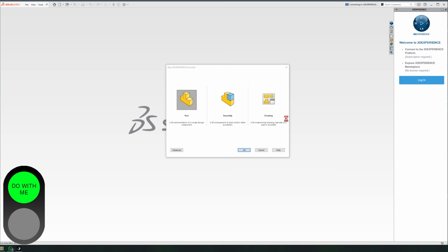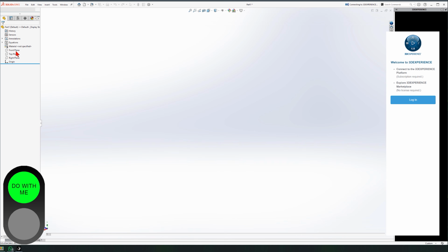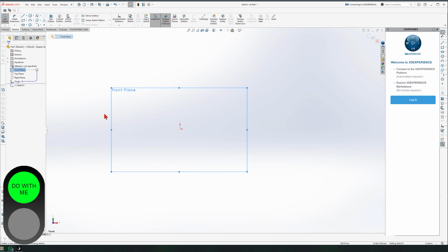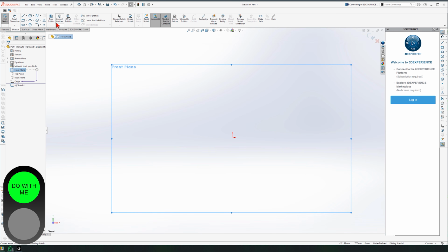I'm measuring the teacan on my desk here, and I give you the values. I'm not going to do any cuts or edits over here, so you can follow in order. We start drawing on the front plane. Then we draw a central line vertically up because we want to revolve everything around that. I have measured its height. It's 88.71 millimeters. Make sure your units are set right. And its diameter is 138. So we are talking about a geometry that more or less looks like this.